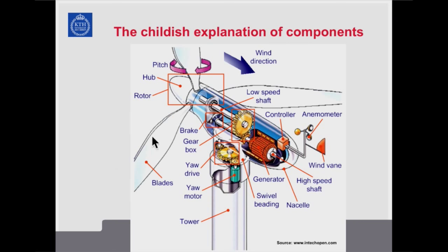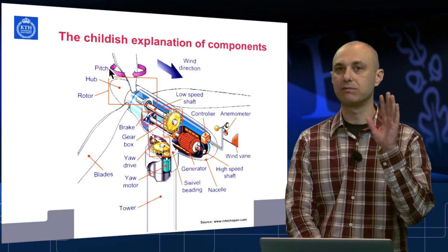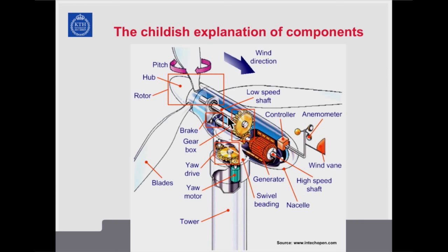First of all, there should be a rotor, big rotor, wind rotor with blades. If the blade is pitching, it would be flipping like this. Then there should be the rotor shaft. This is the main shaft holding the rotor. It has to be supported with bearings, and it has to have, maybe not, maybe yes, a gearbox. The gearbox is transferring the torque and the rotational power to a generator of any type. The electrical generator will sit somewhere here in the nacelle.